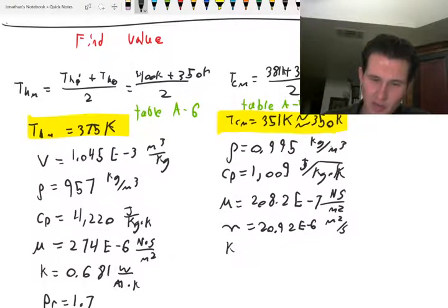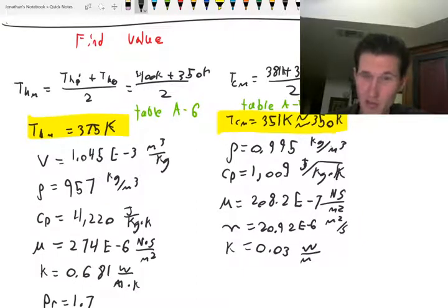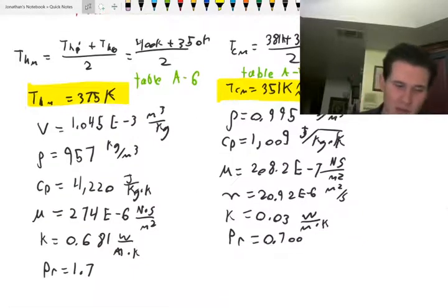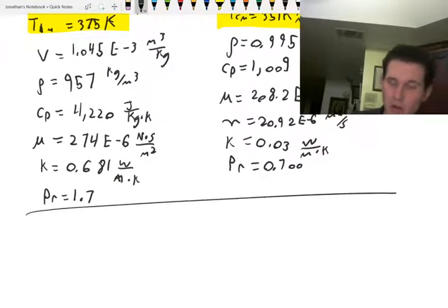And we get our thermal conductivity again. We have a very, very low thermal conductivity for air. It makes a great insulator when it's not flowing. And we get our Prandtl number, how well these fluids are going to mix, essentially, and some other things factored in, at 0.7. Bam. We are done with this section. We now have what we need.